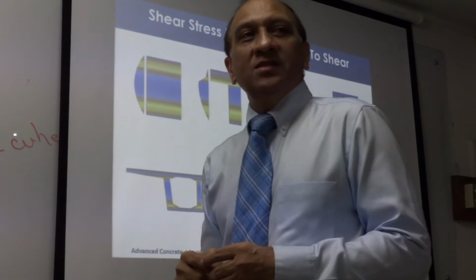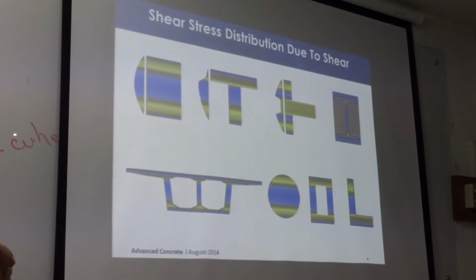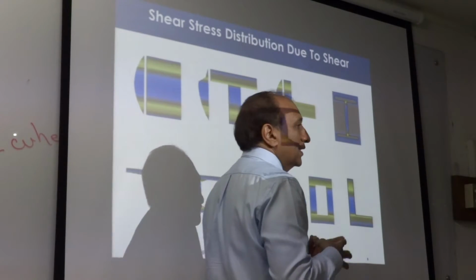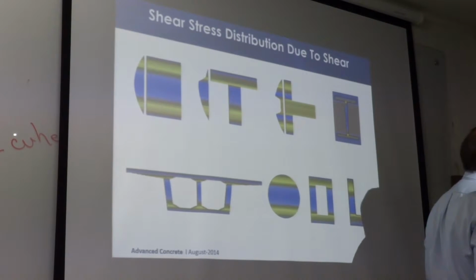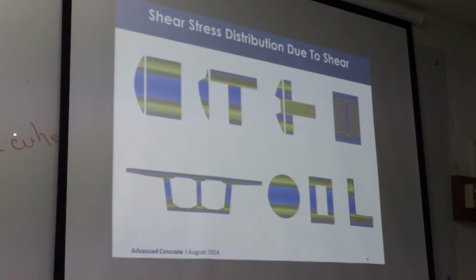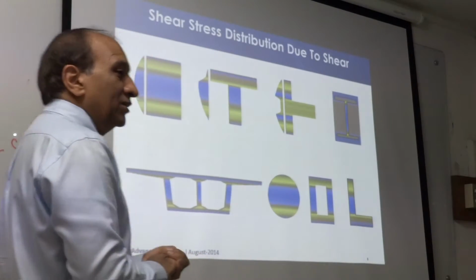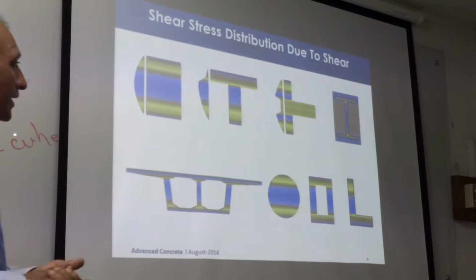It's a perfect, I section is the most, I would say, actually box section, but okay. Box section is the most efficient section of all sections. Steel box section is a perfect section in every way. It can take torsion, it can take shear, very nice in both directions. It can take bending in both directions. It is a perfect section. A box steel section is the best possible section that you can get for bending, shear and torsion, right?